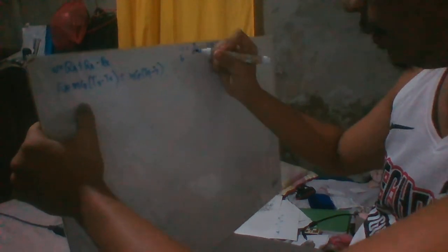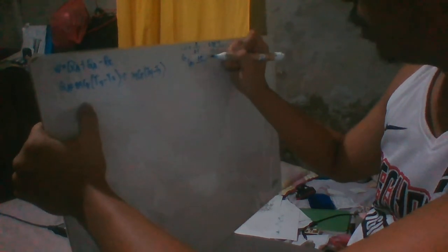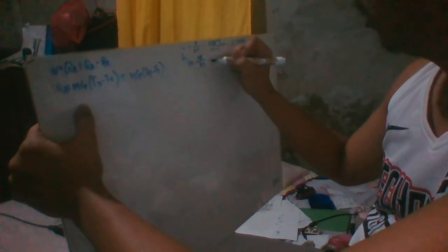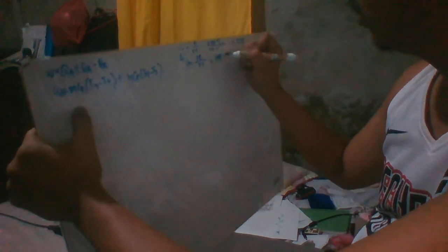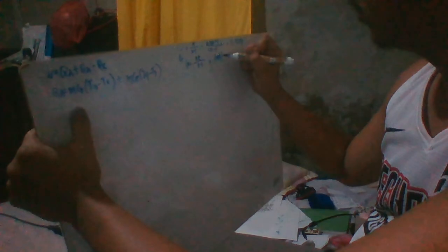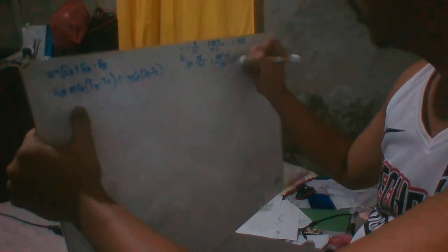And Cp is equal to kR over k minus 1, so 0.287 times 1.31 over 1.31 minus 1, which gives 1.2128 kilojoule per kilogram Kelvin.